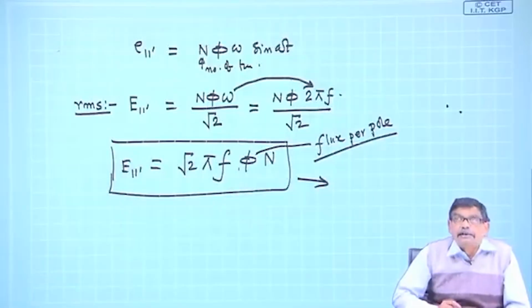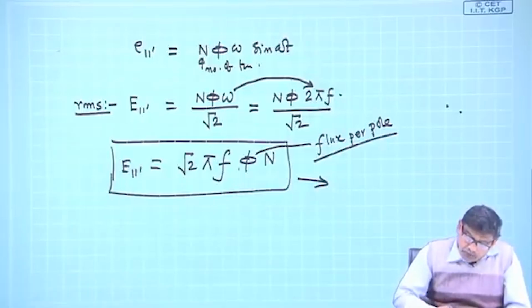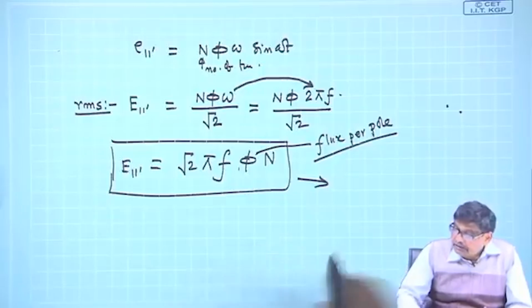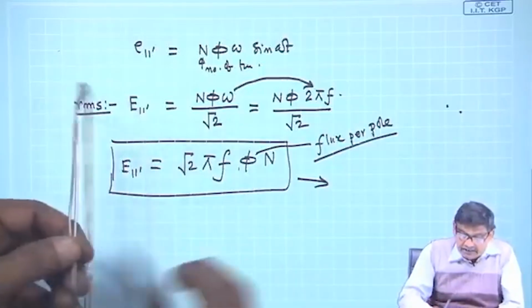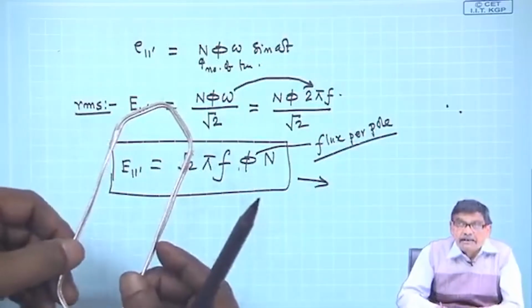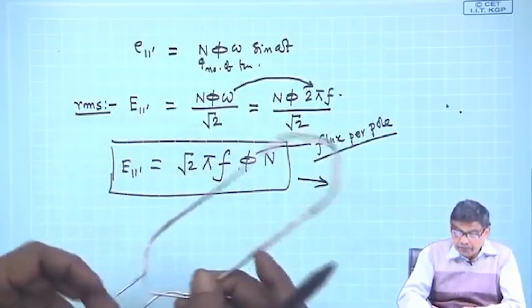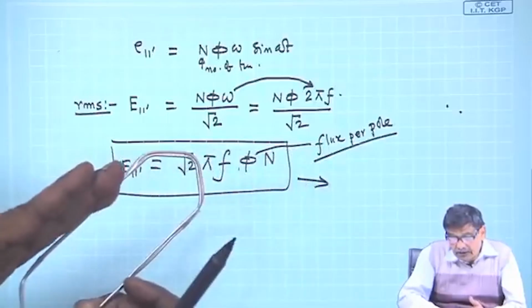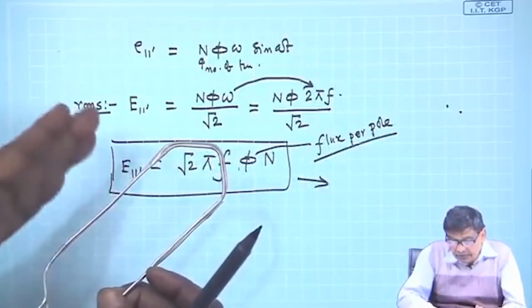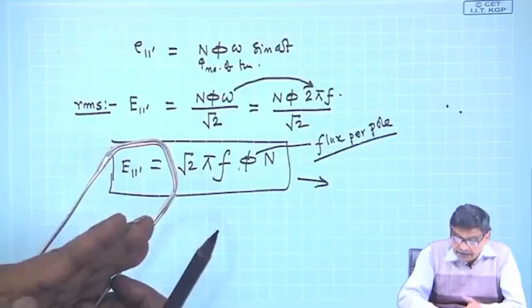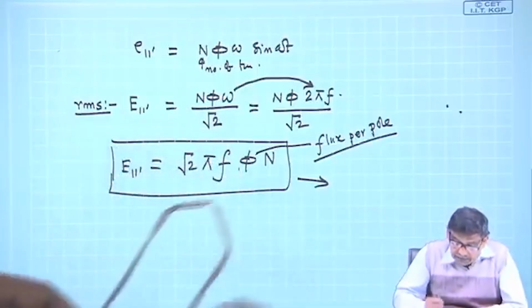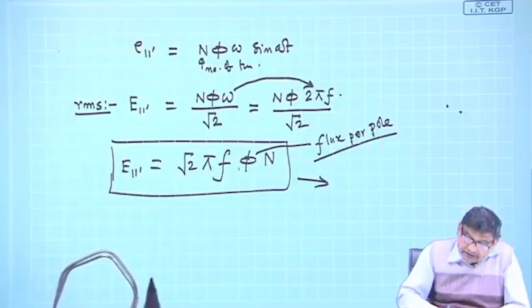You want to generate AC voltage. So, having N number of turns means this coil is having N turns and they are placed in appropriate slots, so that you maximize the induced voltage. That means that if one coil side is under the center of the north pole, the other must be placed under the south pole, and they will be moving with constant velocity.